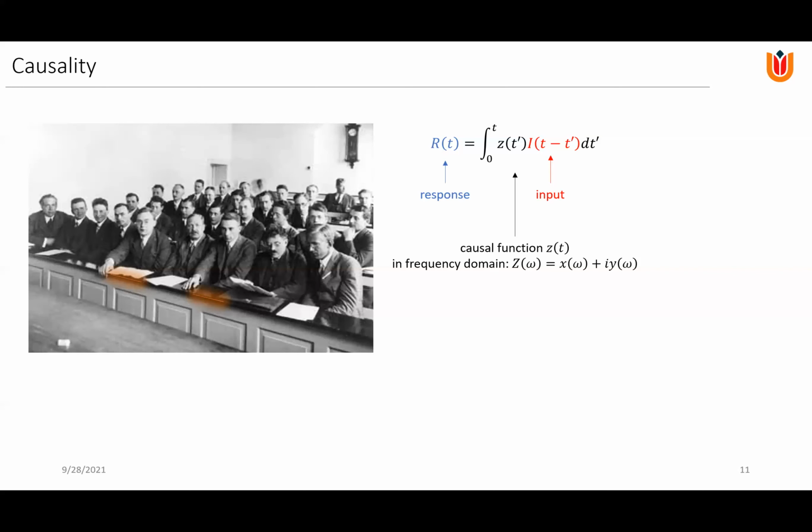So basically, you have a physical system. You apply an oscillatory input with some frequency and some amplitude. On the output, you get a different amplitude and some phase difference, some phase lag, and that is what this response function describes. If you describe it as z of t, then it is a real function, just in the time domain. If you take the Fourier transform, then it has a real and imaginary part, or more cleverly, an amplitude and a phase.